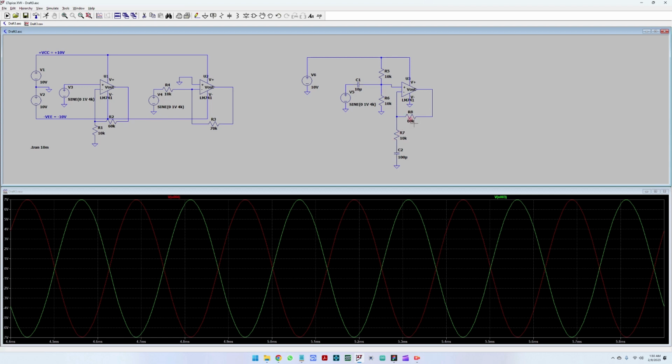Okay, this is great. One last thing that we have to do is to change the value for the power supply, because here we have 1 volt peak to peak. So this is 2 volts. If we're amplifying 2 volts times 7, it's 14 volts, and we're supplying everything at 10 volts. This will be kind of squished here.